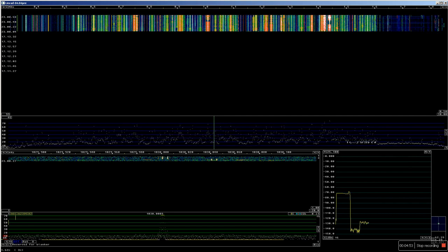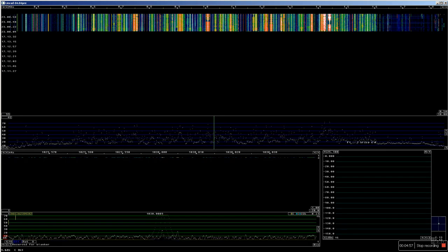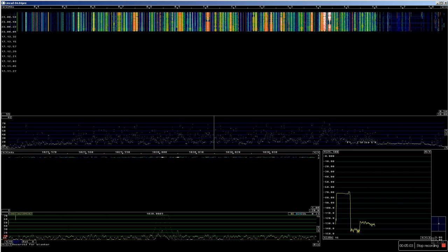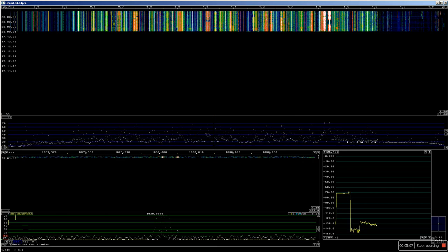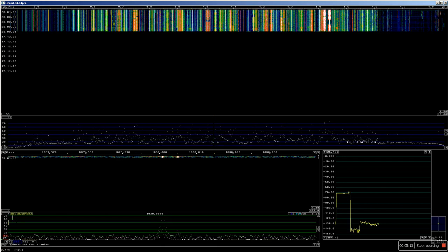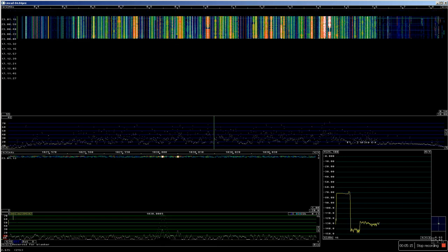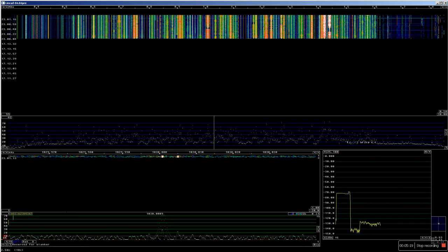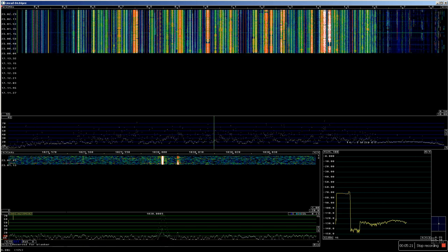That's the outwards arrow on the left side. And to make sure that I'm really measuring the carrier and not so much of the noise around it, I can make the filter a little bit narrower. Like that. And then press F3 to run this faster.